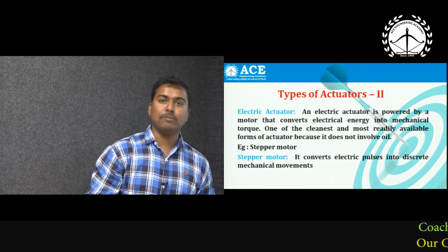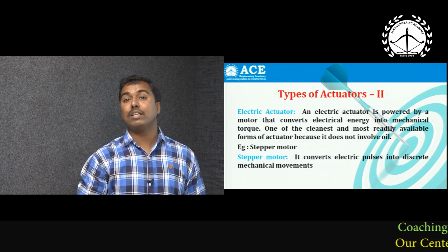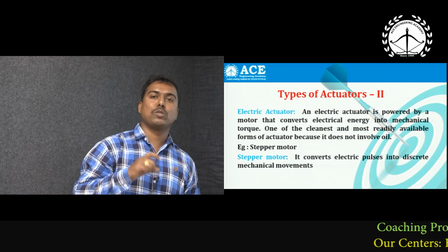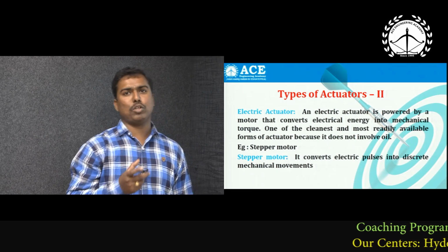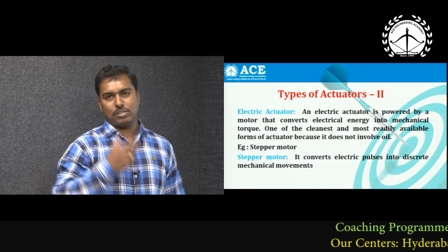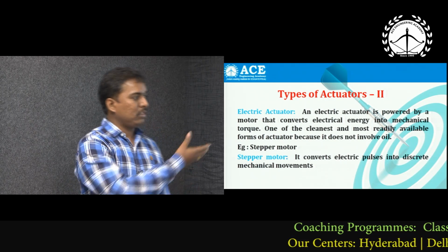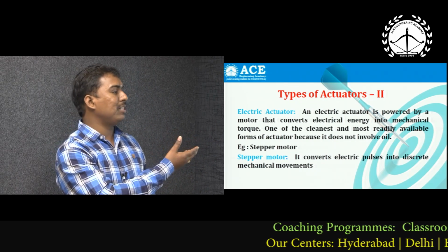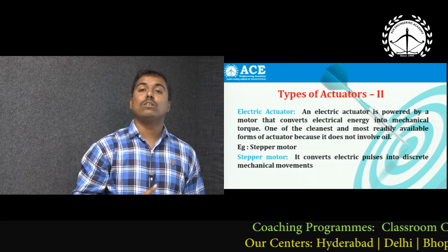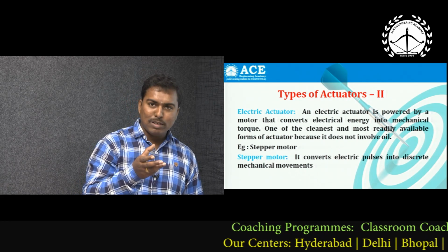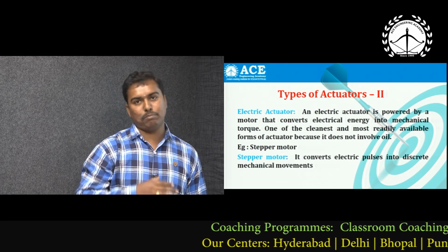Under the electrical actuator, a stepper motor is given in the syllabus. So the student is to get an awareness of what a stepper motor is. You may have studied normal motors, but here you are going to study the stepper motor. What is a stepper motor? It converts electric pulses into discrete mechanical movements. That means the mechanical movement is going to be discrete, on and off type, a digital type.